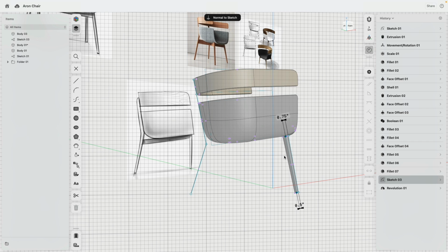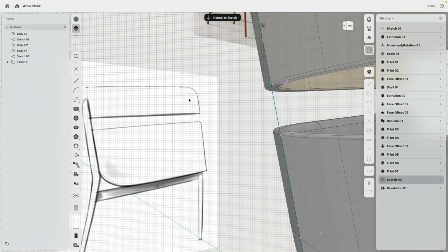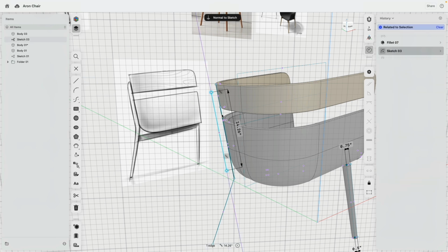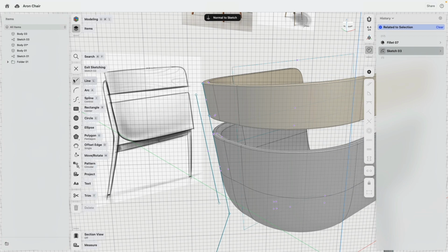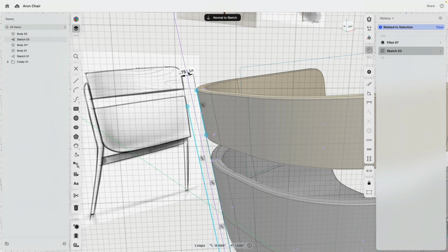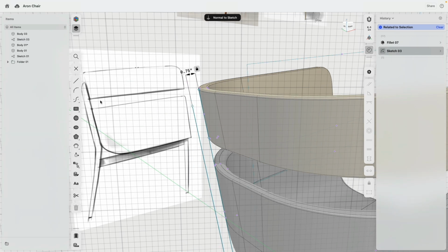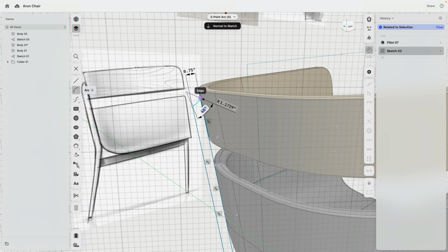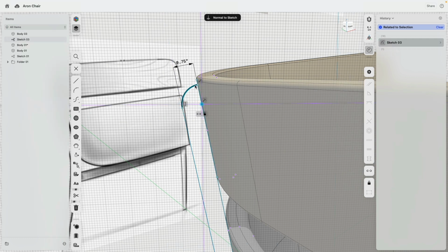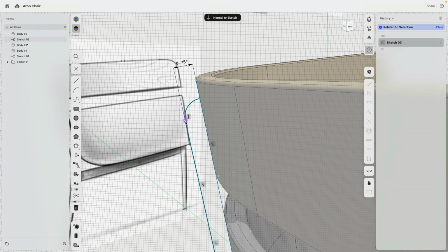And what did we say? 0.75. Okay, so we will do the following. I will draw here a line to there and say U and U parallel. The distance 0.75. Okay, very good. And then I make here a nice arc, U to U tangent. This one goes onto that line. Now this is actually 90 degrees. Very good. This can go down a little bit.